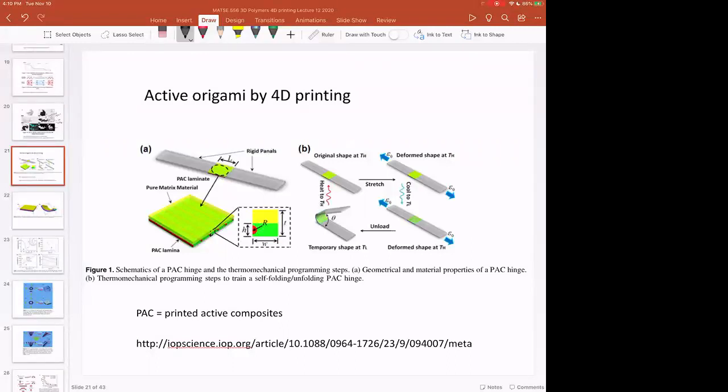Okay, the last thing we'll talk about, and we'll get off of 4D printing, but I wanted to give you a couple different modes of how this might work, is that by deforming objects in different ways and by using this heating and cooling, using this idea of a bimetallic strip or a bimaterial strip, you can get different types of deformation depending on the mechanical properties and depending on the material construction of this laminate. And so here's the reference right here.